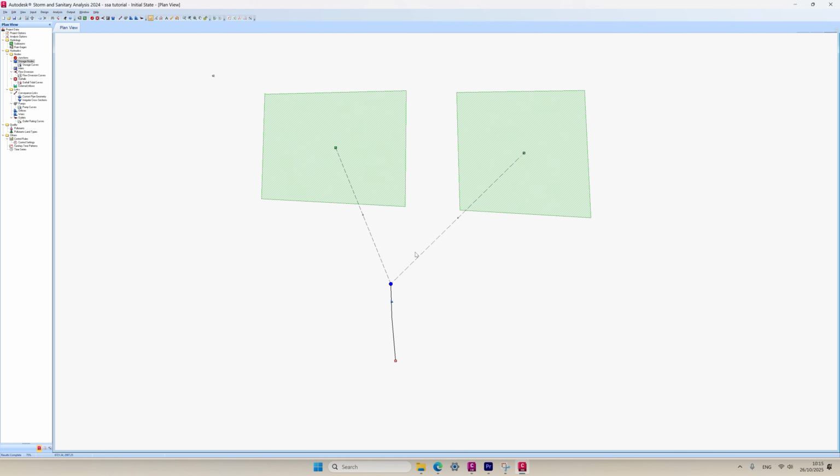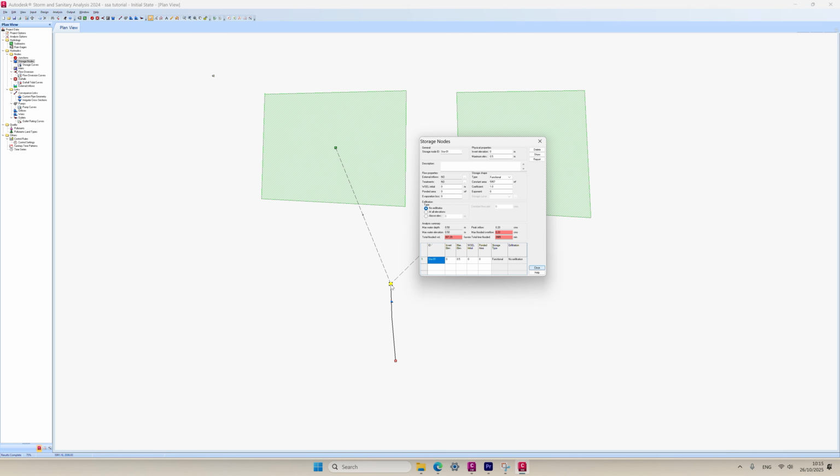Click on OK. Let's see. So right now you can see there's still a bit of flood. It dropped down to 387 right now, because we added the area of detention ponds. So right now, our site is still flooding, our detention pond is still flooding. We could also add a little bit of infiltration for our pond. So let's just give it a very small number, like 0.1 cms, and see how that will help our pond.